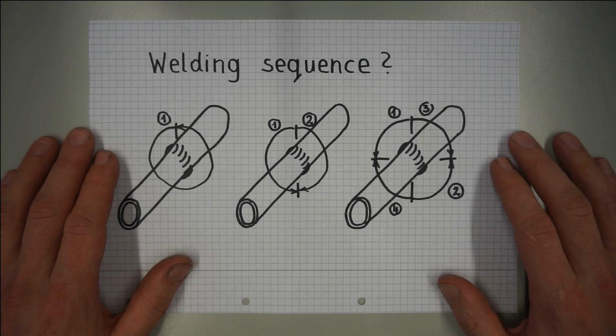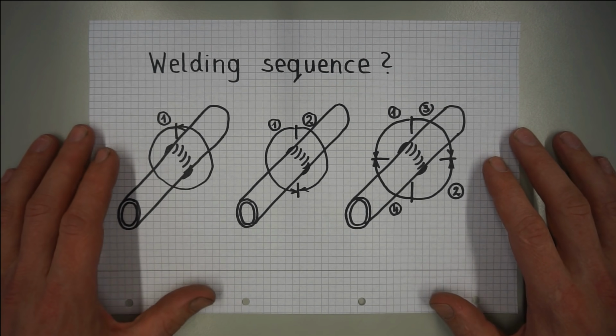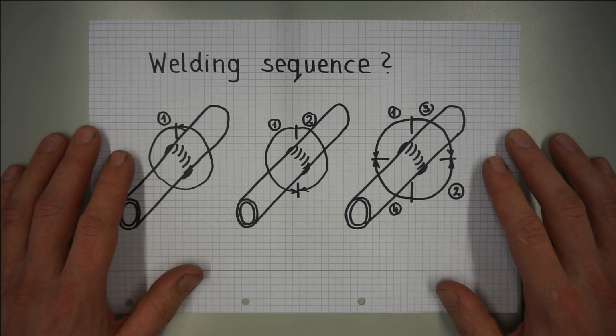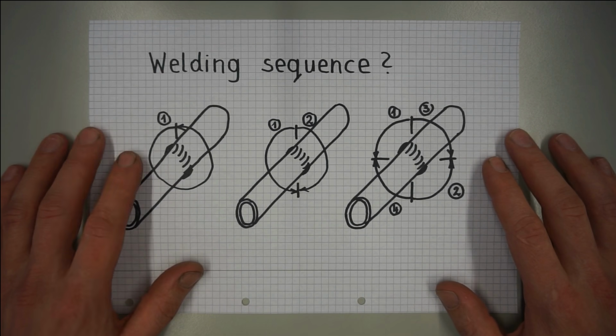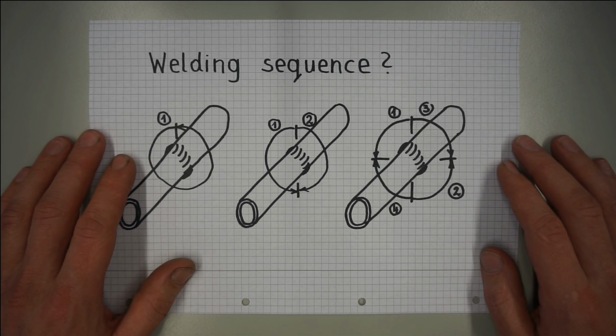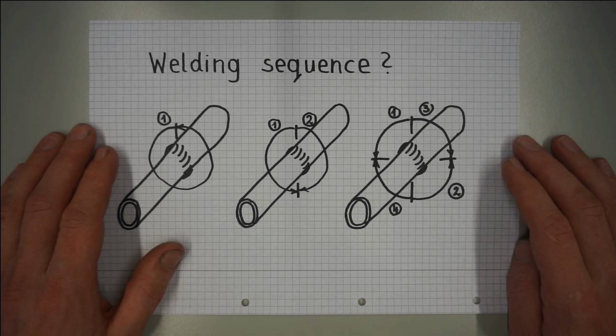This is, for example, because during welding the workpiece gradually heats up, which in turn gradually satisfies strategy number 1. However, at the same time the workpiece may become less flexible for the heated spot expansion, which dissatisfies strategy number 2.